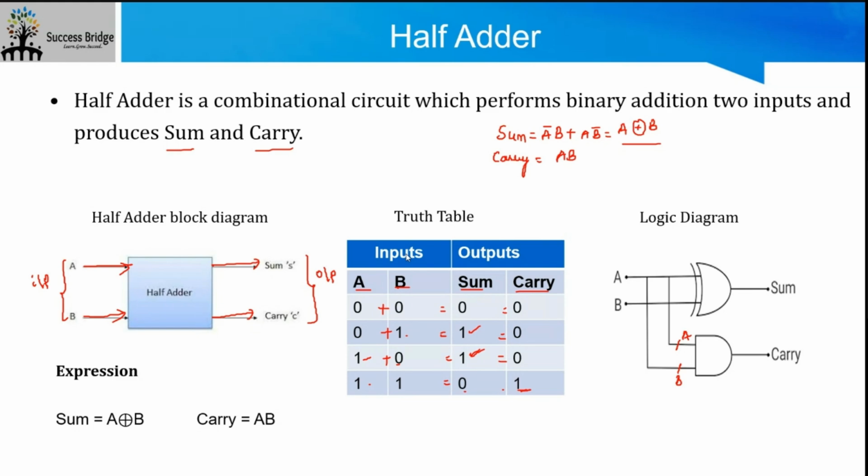XOR gate. Right. So 0,0 and 1,1 will always, whether the inputs are active high or active low, give a low output. But given the half adder, we get a proper carry when both inputs are active high.